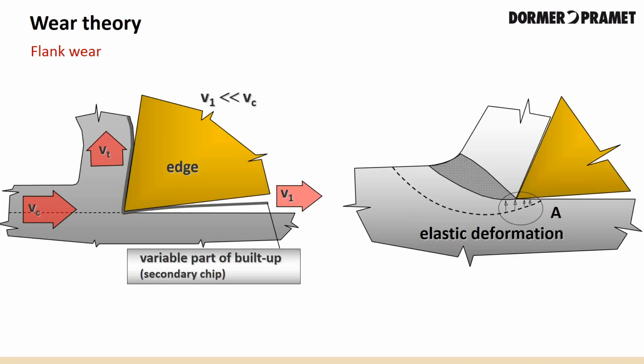Increased flank wear is caused by outgoing particles from built-up edge. In most cases, flank wear is caused by the contact between the workpiece and the flank of the tool, and will in some cases cause elastic deformation, a buildup of material beneath the surface finish. Very often this phenomenon will occur in fine turning when the selected feed is too low and the tool basically does not cut but instead is forming the chip.